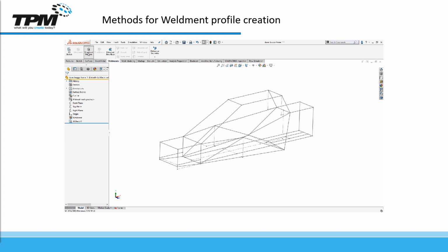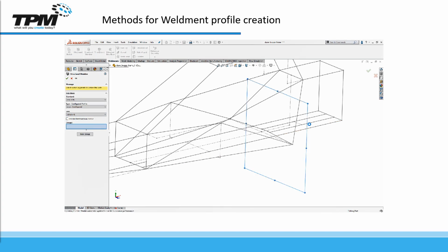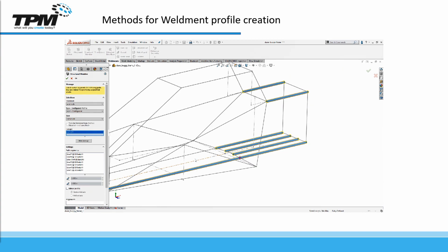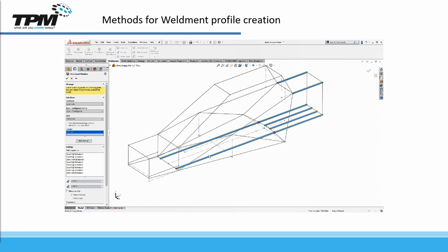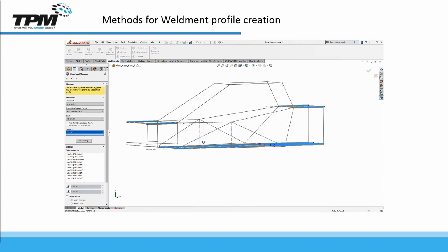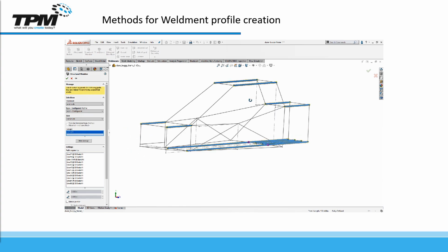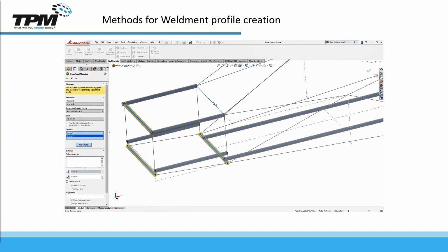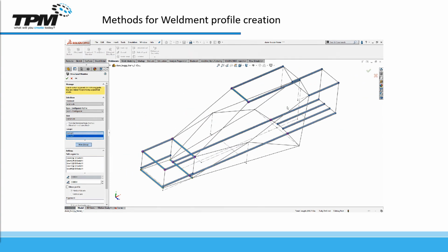In this sped up video, I create the groups of my Weldment profiles based off of their orientation. If there are multiple sketch entities that are in the same direction, I select those first so that they can all be grouped together. For this frame, the horizontal and vertical groups of the frame are also the important junctions in the frame, so it is critical I pick those first.